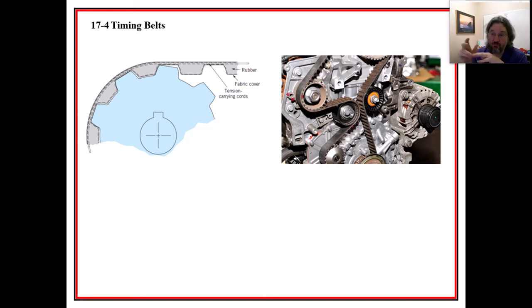So if you just have one timing that's set for every speed, you can have the exhaust valve opening too early and let unburnt fuel out, or anyway, you can change the emissions. You can also change the temperature.